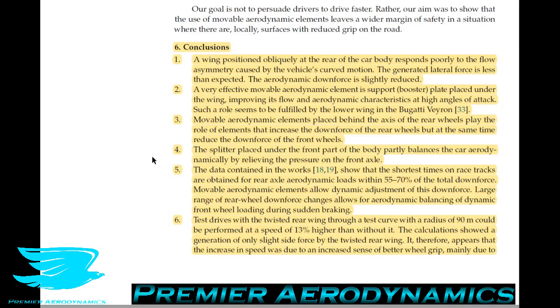So this can potentially be good, but if you need a certain stability, like a certain distribution of forces from front axle to rear axle, changing that could then result in instability to the car, which means that the handling reduces, and it means you can't go around corners as fast.